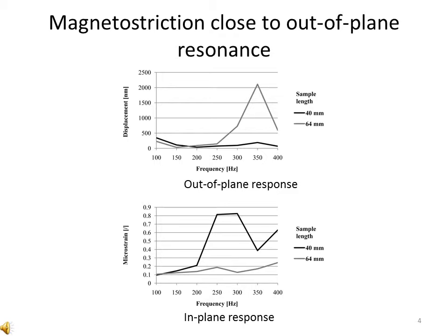Magnetic excitation was applied at frequencies ranging from 50 to 200 Hz, resulting in fundamental magnetostriction harmonic of 100 to 400 Hz. Response was measured in the in-plane and the out-of-plane direction. In contrast to the control measurement, the altered geometry of the sample resulted in mechanical resonance, which proved detrimental to the quality of the measurement.